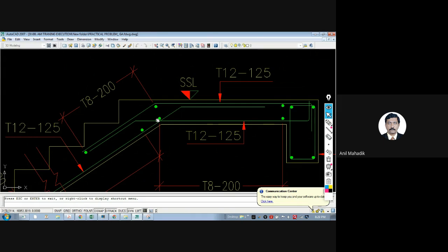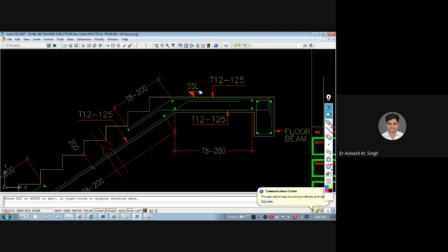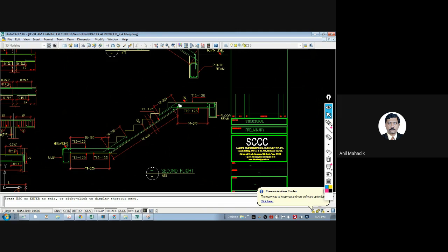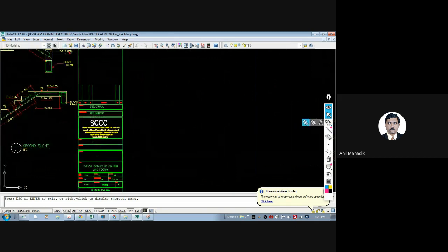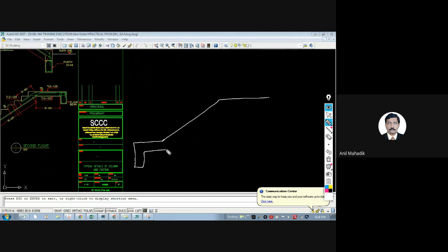Okay sir, I had not seen it here, that's why I asked. No, this is a must actually. This is a common mistake. People directly put the steel like this, which is a very wrong method. Your slab would be wasted.